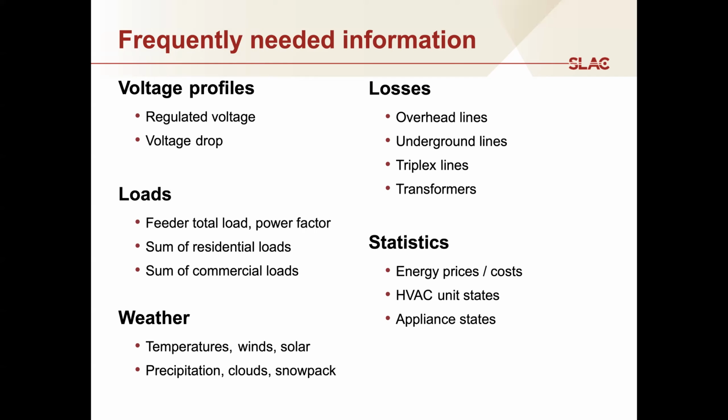Weather data is obviously crucial, as I said before. Very often we have to provide weather data in order to get realistic results. Although it's not common, it is interesting to provide a static weather input and do things like a step change in the weather in order to identify the model of a load or the model of a device's behavior in response to temperature changes. This can be particularly useful when you have to try to figure out why your model isn't working the way you expect it, and try to isolate which aspect of which object is giving rise to unexpected behavior.